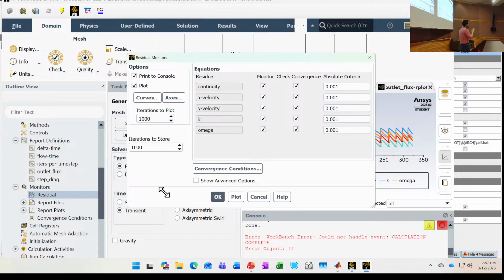Now, we will talk briefly about turbulence in more detail. The k has to do with the amount of turbulence you have. Omega has to do with how that turbulence is being dissipated. It's the k-omega turbulence model. It's a Reynolds-averaged Navier-Stokes method. All right, but for the first three, you should have a basic idea.